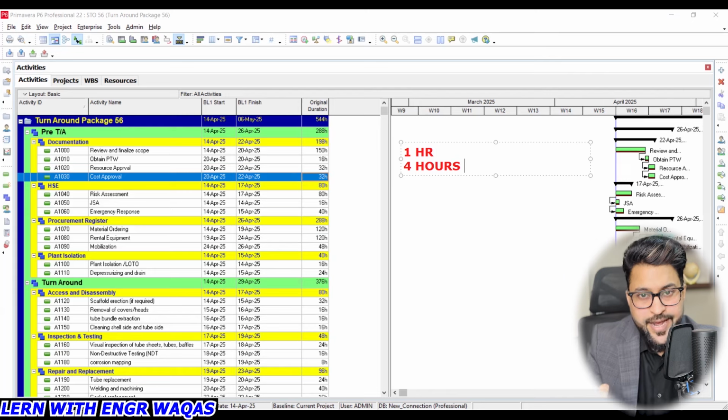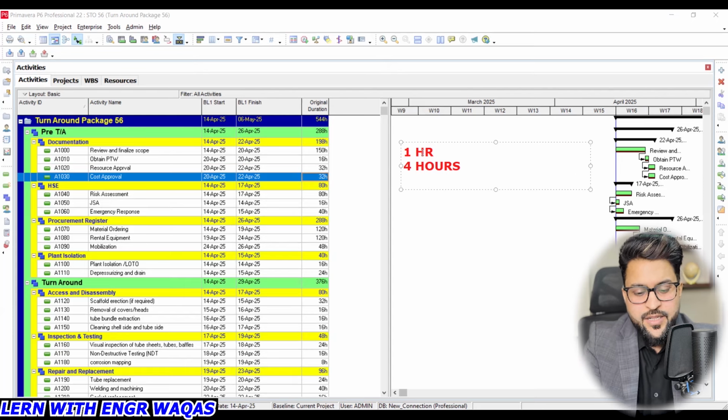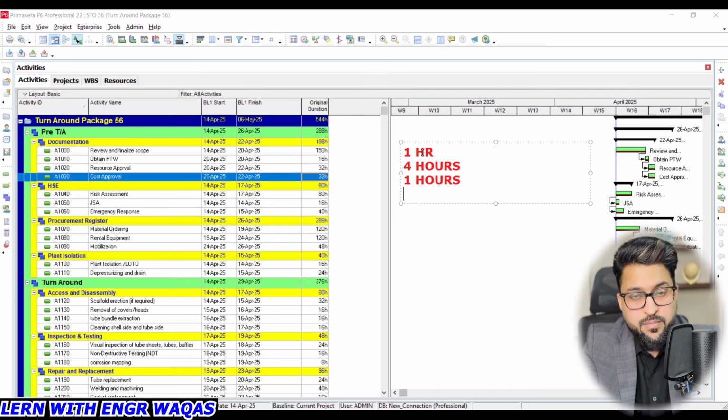You need to take gaskets out of that valve, you need to replace them, you need to analyze them, right? So maybe it will take 4 hours, and then you are closing and it will take maybe 30 minutes. So that is already like 1 hour to redress and reinstall it. And then you are going to make some hydro testing, pressure testing. It requires like 1 more hour.